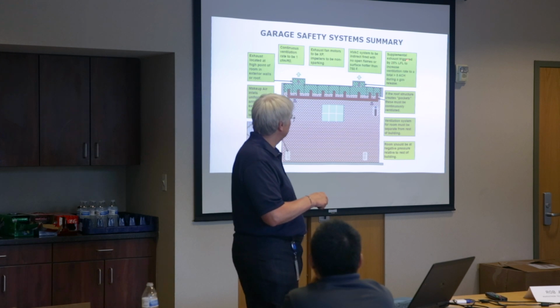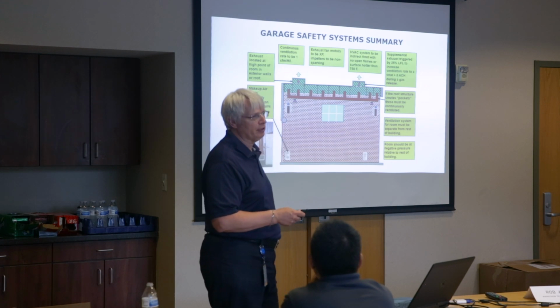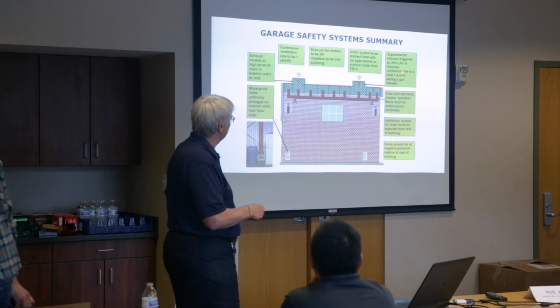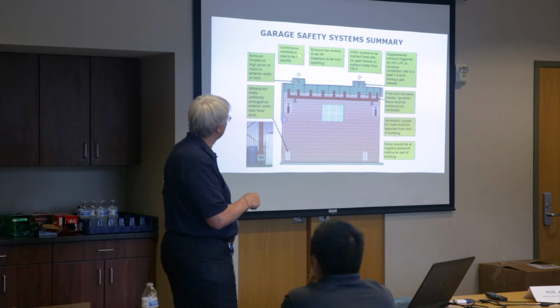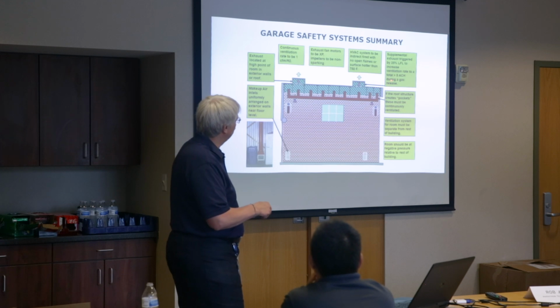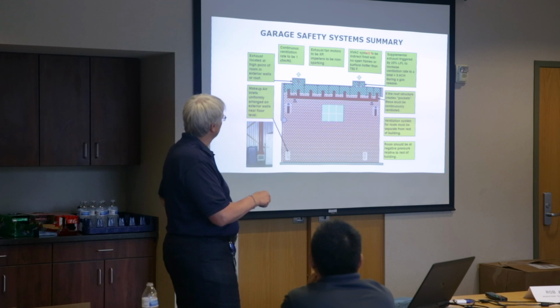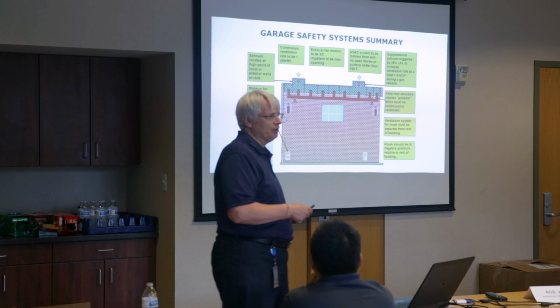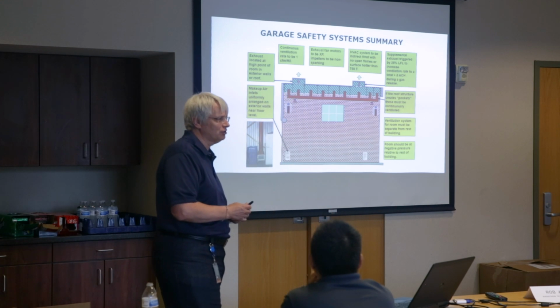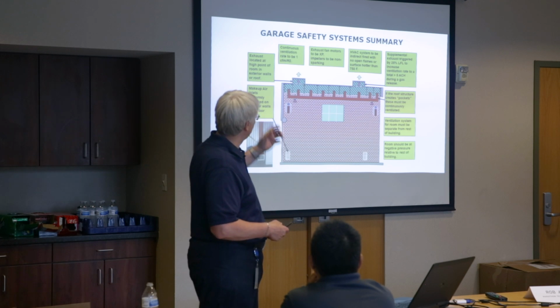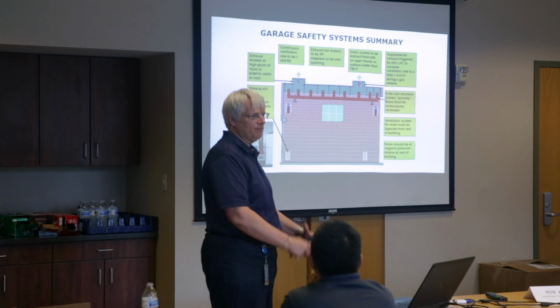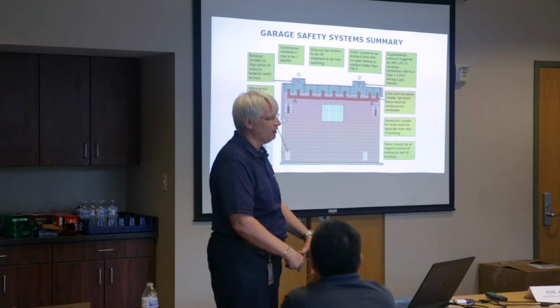It's triggered at 25% of the lower flammability limit, or LFL. That will increase our ventilation rate, in this case, from 1 CFM per square foot to 5 air changes per hour. It's a bit annoying that they go back and forth between these two units and these two ways of thinking about it. But if you think about it like this, 1 CFM, so that's 1 cubic foot per minute, and an area of 1 square foot.